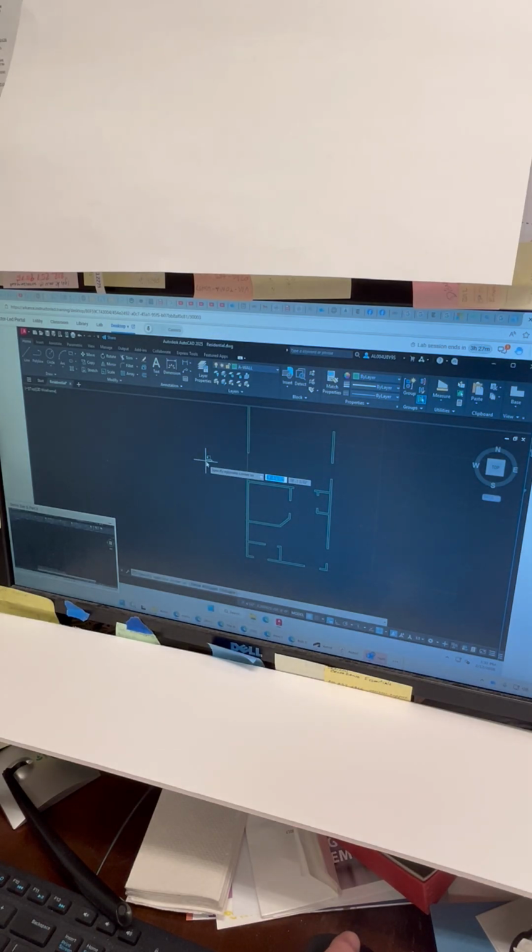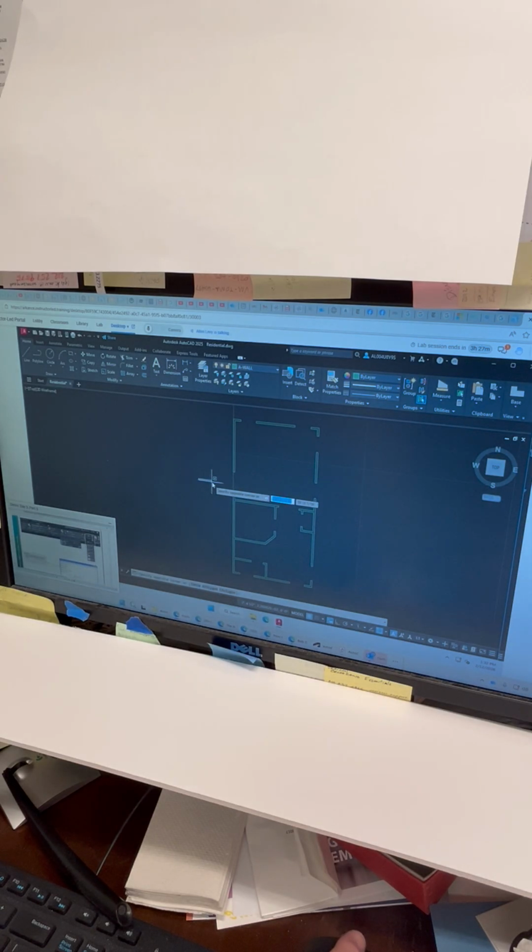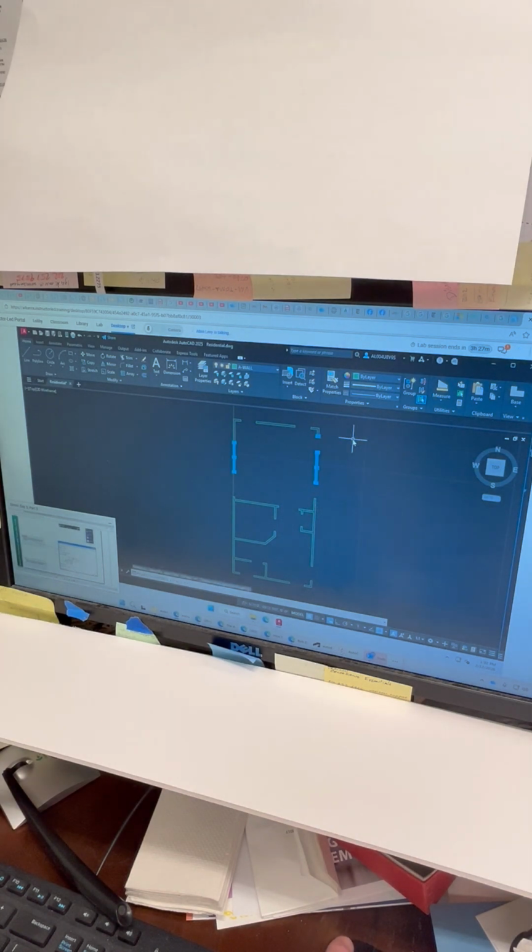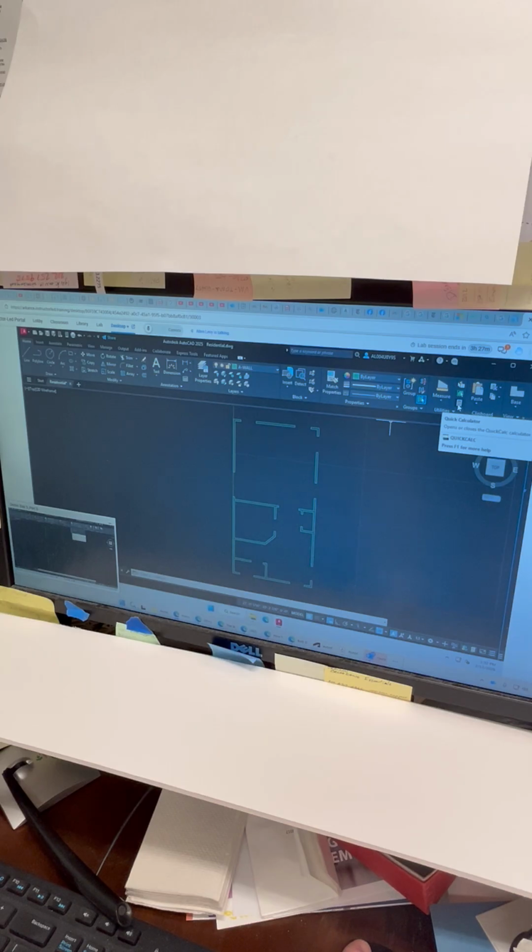Now, there are other things that are listed in our workbook, and they're sort of old ways. Here's a tool called list. And I'll be honest with you, list was a command that we used to have to use before we had palettes, before we had the property palette. So to show you what I mean here, type in list. There is a command for it in the properties drop-down palette, but I usually just type in list. So I'm just going to type list, L-I-S-T, and hit enter.